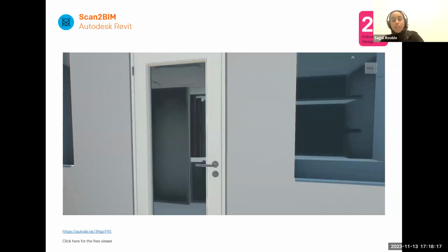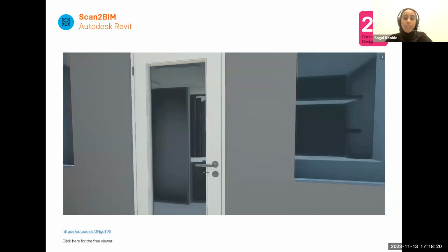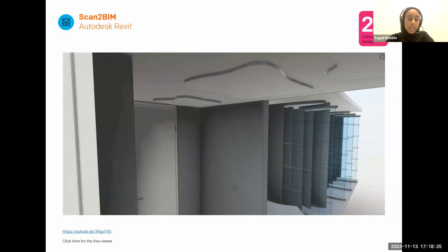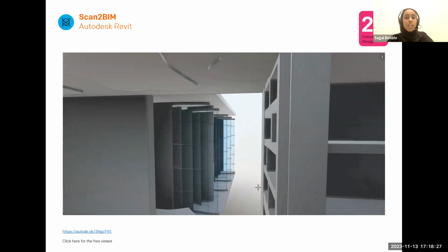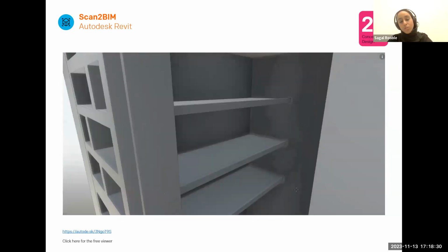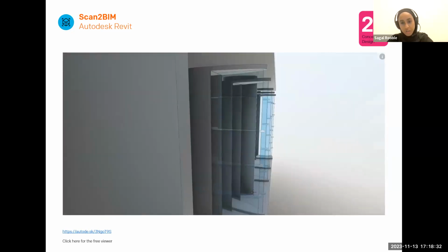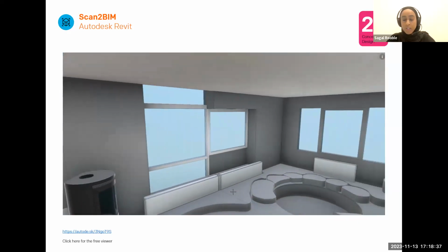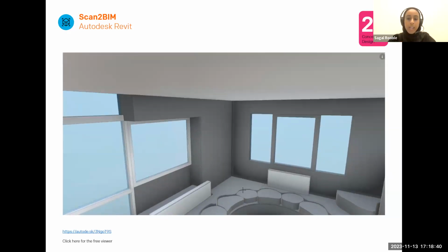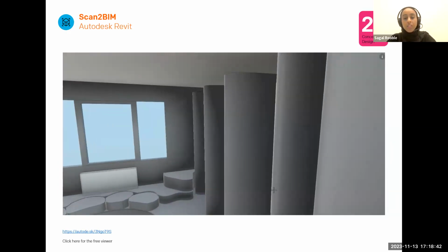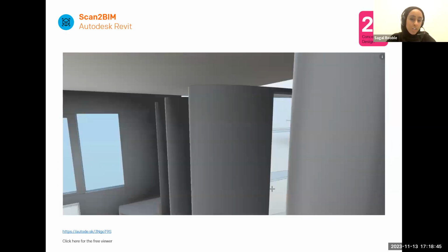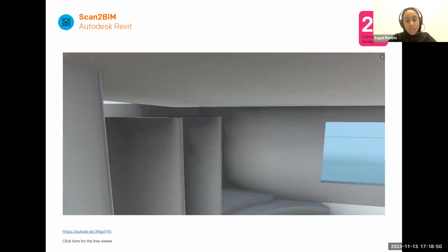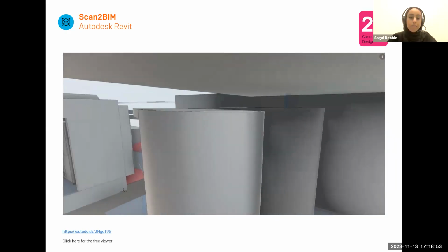Once you're able to capture what's on site, being able to model it in a 3D modeling software like Revit is key, because then you can get something that you can actually work with. So the point cloud would get you, once it's modeled, to a physical or 3D representation of the physical asset in a geometric form. So we're able to then use this as part of that process, and it's actually tangible. It can be used to create drawings, it can be used to model, create visualizations from it, etc.